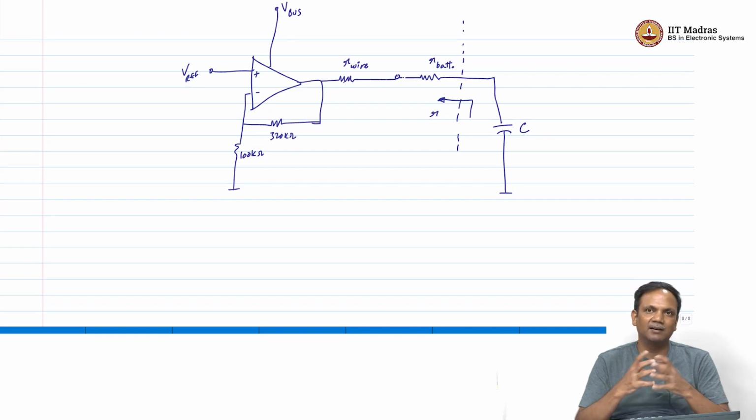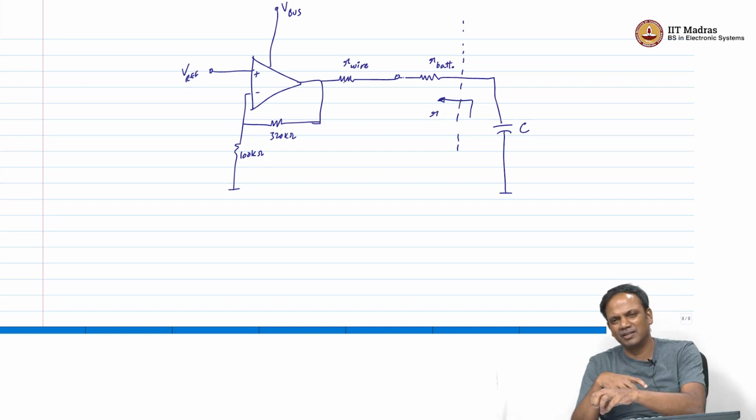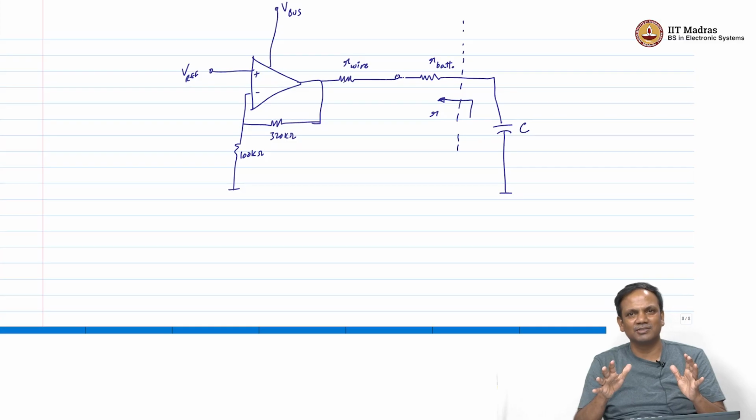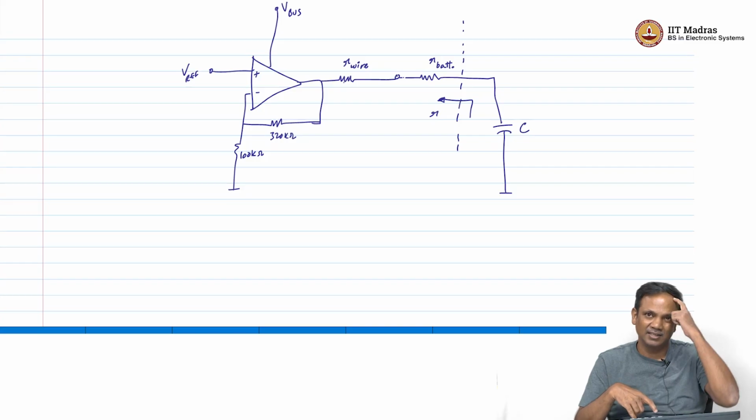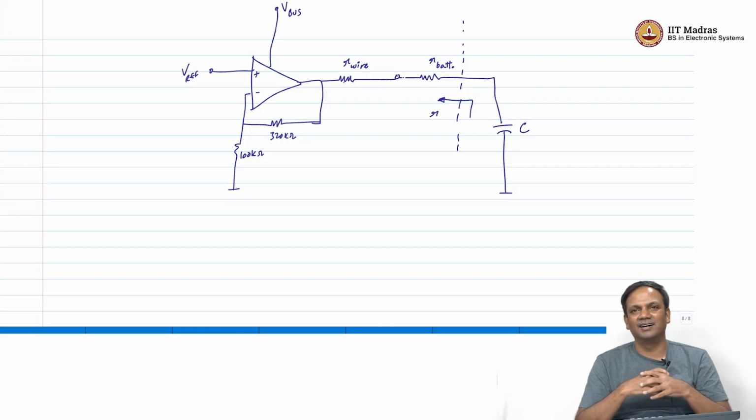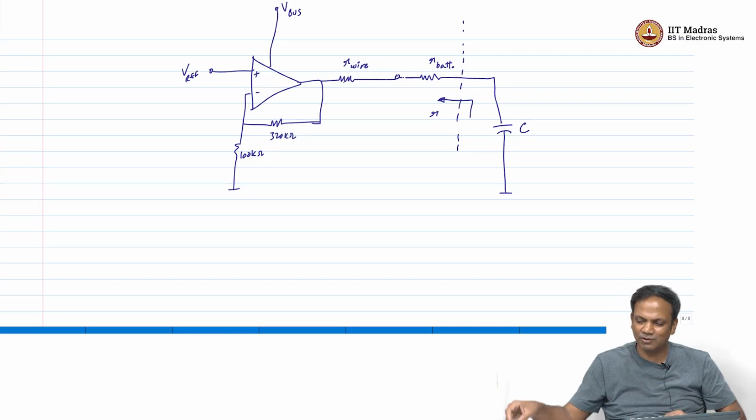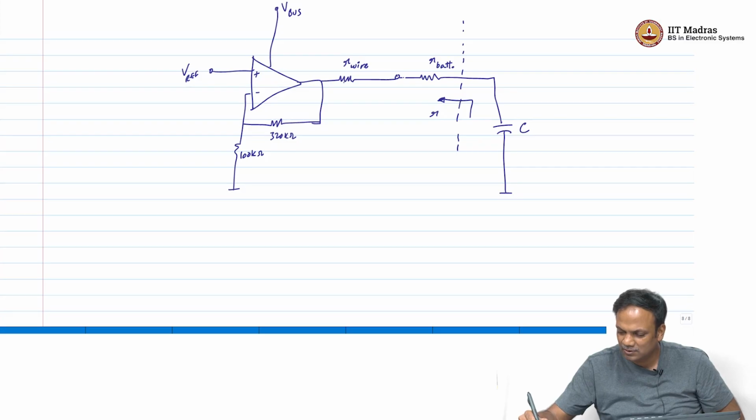So, with that you assume, I have a 1000 mAh battery, maybe I am going to charge it with 1 ampere of fast charge current, and I am willing to tolerate maybe a 50 millivolt drop. So, R wire and R bat put together has to be in that 50-100 millivolt range. That is how you would think about it. It is possible it might be a little higher, but at least for the purposes of a first calculation you can say that.